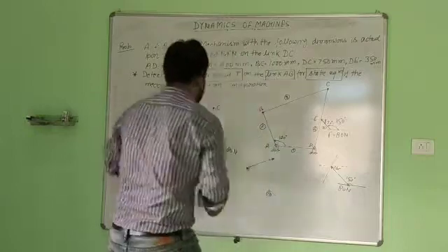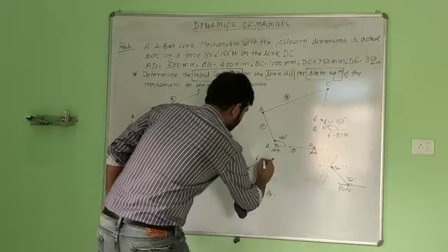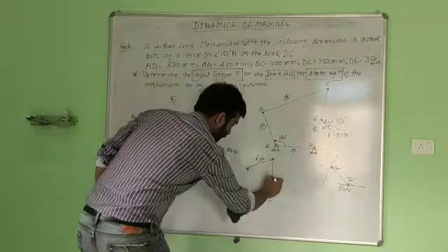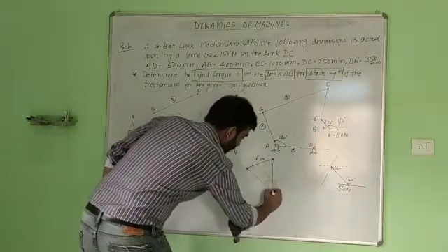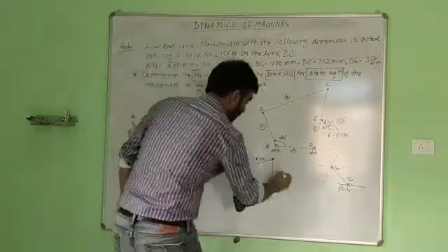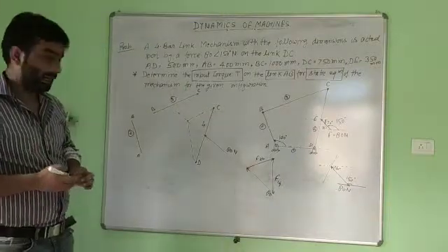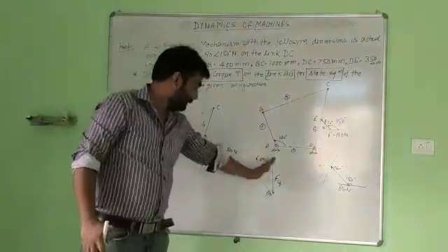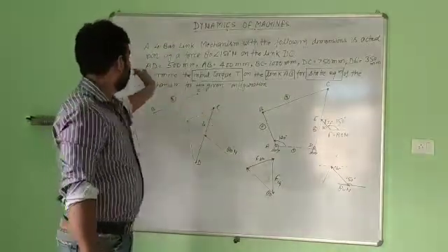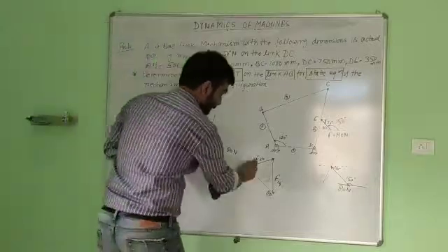this force, which will be F, the force by member 3 on member 4. Now we have direction and connect this one to this one. We will have F, the force by member 1 on member 4. So we can get this triangle by taking the condition that the mechanism is in static equilibrium. So we will have this force triangle.